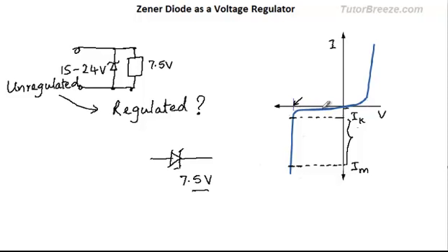And you can also see this from the VI graph, because the reciprocal of the slope of this graph, which means dV over dI, will give you the resistance, and since the resistance is very large, the current is almost zero. And when the current is almost zero, then the diode is off. The diode is not conducting any current.